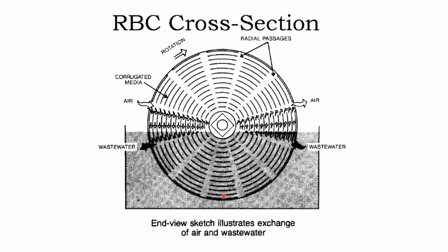The microbes are going to suck up as much food as they can get. We've got wastewater in these systems, and as it comes above the surface of this channel here, the wastewater is going to start falling down. As it falls, it comes in contact with the air and aerates the wastewater, so we have a nice aerobic environment here, free of odors.